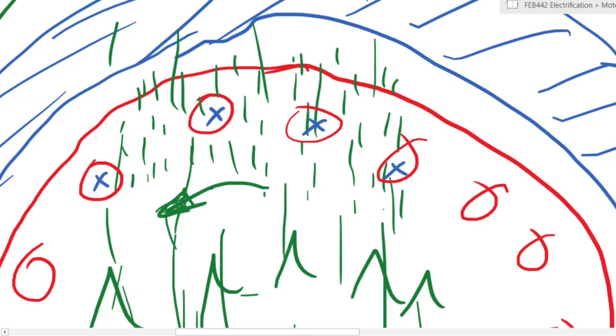Now, in that particular case, you have a magnetic field, your rotating magnetic field, which was created from the action of the windings in the stator having power applied to them. That rotating magnetic field is moving through the rotor, and it has now induced a current within each of the rotor bars. These rotor bars are like wires. They are like any other conductor. They will conduct current.